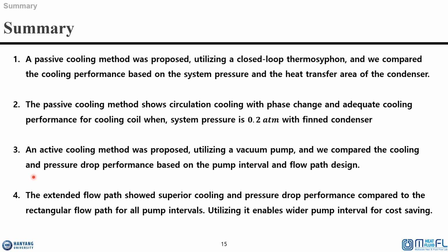Third, we introduced an active cooling method utilizing a vacuum pump and compared the cooling and pressure drop performance based on the pump interval and flow path design. And first, by utilizing the extended flow path, we enhance the cooling effect and reduce pressure drop compared to the rectangular flow path. And this allows for a wider pump interval in the design, potentially leading to cost savings.